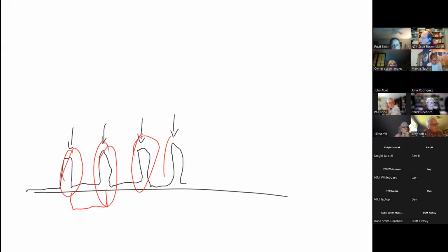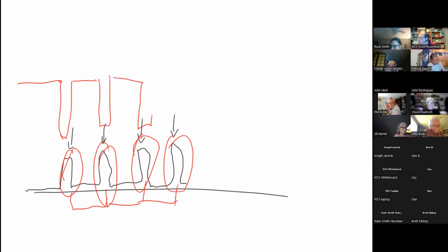So what happens is your radio, during that period, takes the gain of the receiver and drops it really, really low. Effectively saying, you're not going to get any signal there, but you're also not going to get any noise. So you're going to have these little blank spots. If you're listening to somebody's voice, it's not really a big deal. But with certain other modes, it may very much matter if the signal goes away during that time. And that's called a noise blanker.